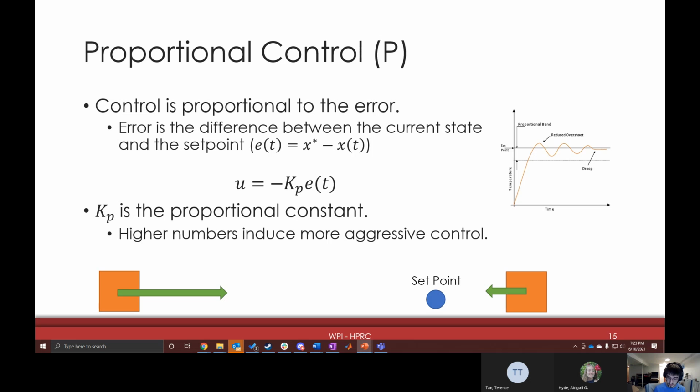So, does proportional control make sense? Yeah, that makes sense. Would the system be better than Bang Bang? So, Dasha, I'll say it depends on what you're doing. In some situations, Bang Bang can actually be the most optimal way to control your system, but you might need to put in a lot of effort to find what that optimal type of Bang Bang control is.